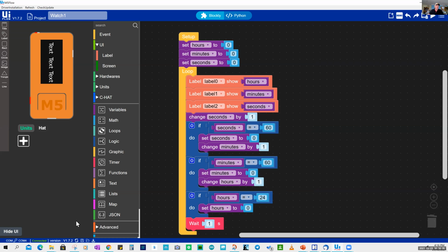So let's check that we're connected. If I go back to my M5 stick C, you need to reset and put it into mode 2. That's USB mode. So remember, reset 2 clicks of button B and wait until you get the USB icon. When you get that, your M5 stick C is ready. It may be that you get the wrong icon, so just repeat it until you get a USB icon to let you know that you're in mode 2 communications with your